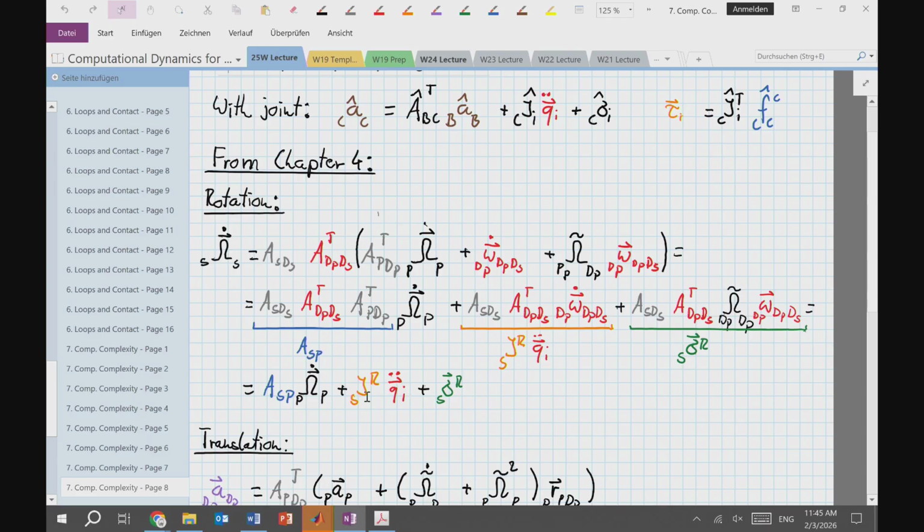It is something that I can write as a Jacobian times a joint acceleration, where this acceleration here, this omega dot, we wrote as R times q double dot. We had this expression where we said this is some Jacobian R times q double dot, and then I just redefine S times dS times A_p, dS transpose times R as this orange Jacobian here.